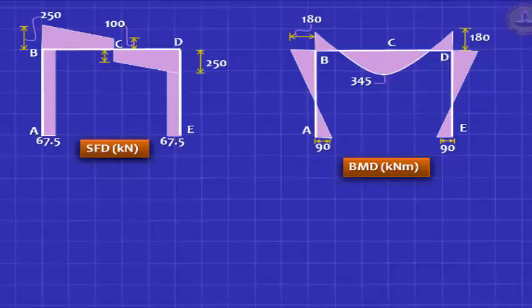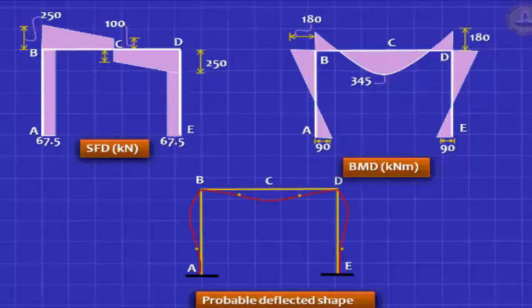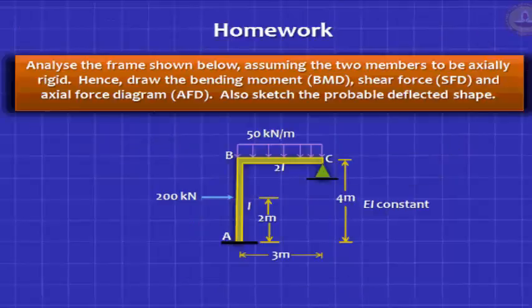Okay, so you had 180 kilonewton meter at the joint on top, you get 90 kilonewton meter, and this is the deflected shape. You see how this matches the deflected shape. Wherever in the beam you have sagging in the middle region, you have positive moment, you have hogging, you have negative moment, and so on. And the point of contraflexion in the column will be at 1/3 height.